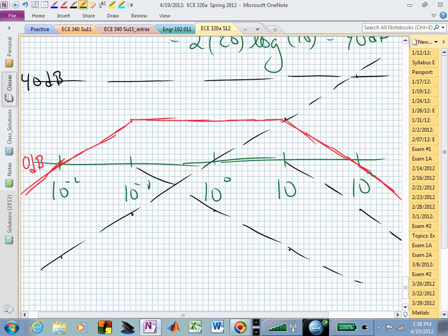And there you'll get that 2, that power, and that will give you a different slope. If it's a pole, it will be minus 40 dB. If it's a 0, it's plus 40 dB. Does that help? Other questions on the magnitude sketch or plot?